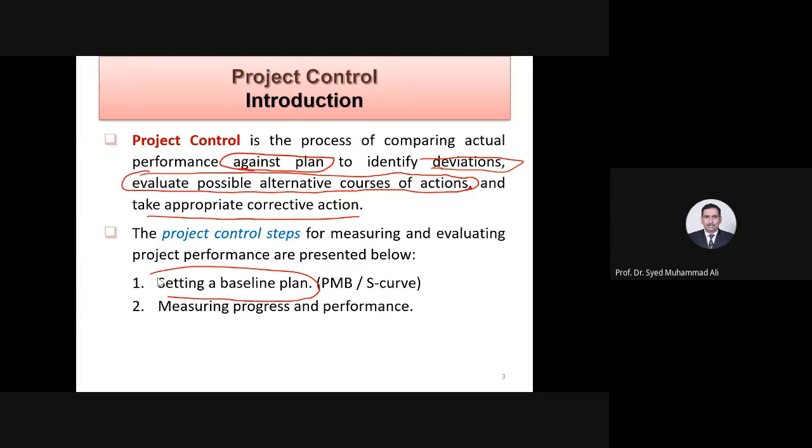So on a daily basis, almost, you will be measuring your progress, your performance. Comparing plan against actual. Now you are able to compare it. Every day from the field in your office, you get the progress. Today we worked from RD 0 plus 300 to 0 plus 900. So this is the progress for today. So you have to have the feedback.